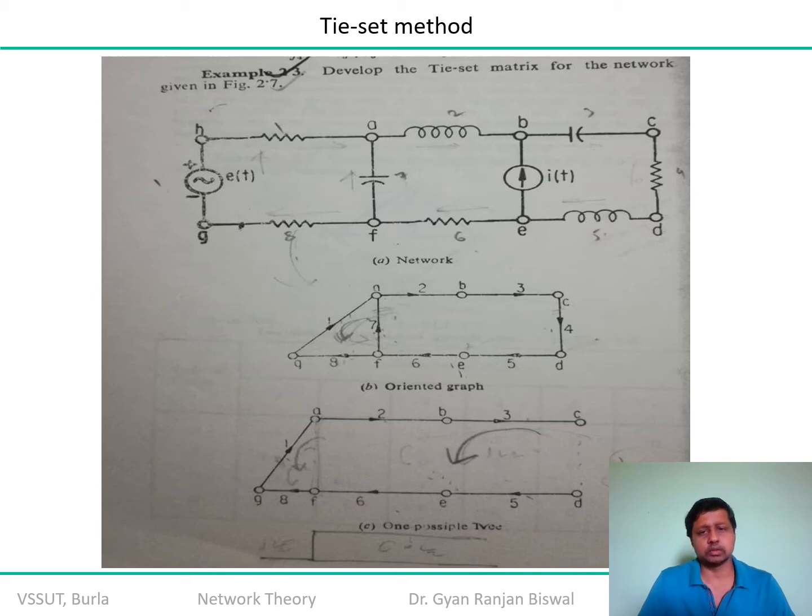Okay, so that allows current to pass through it, whereas the I of t is basically indicating the blockage in one way, the sustainability of that much amount of current. That is why you are replacing it with the open circuit, whereas the voltage source you are replacing with a short circuit. Okay, fine. And for the rest of the elements, whether it is any RLC element, you are going to simply replace it by a hard line. It is not necessary that you follow exactly the same replica. You can draw it freehand. Okay, you can draw it freehand.